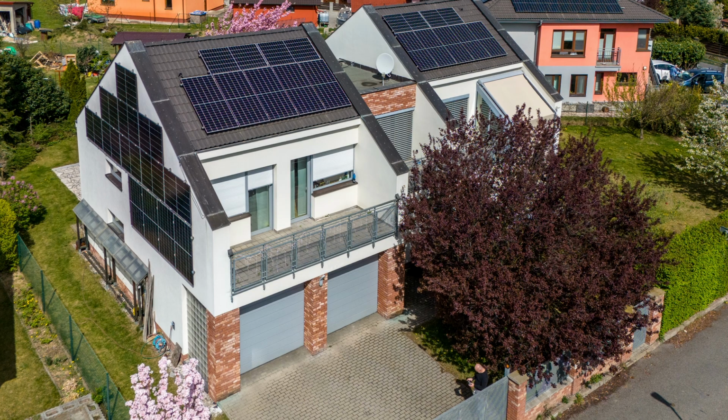Also, I want to use the solar panels for charging the cars, and the inverter is 10 kilowatts as well, so an 11 kilowatt wallbox is perfect. In fact, it's too much most of the time, because the panels give 10 kilowatts only at peak, and they are divided in half between southeast and southwest direction, so most of the day it's actually less. I actually do not know if they ever output the full combined power due to the split in the two directions. So if I want to charge the car from the sun, I need to decrease the charging power to match the solar output minus the house consumption.